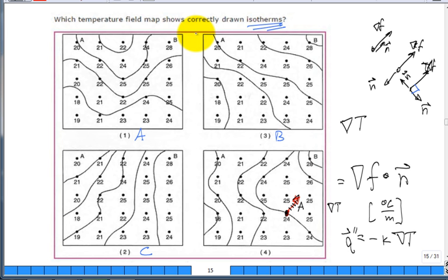True? So one goes in one direction, the other in the other. So now, I don't have time. I was going to give you a chance to catch up, those that missed it, but sorry. It's A, it's in that direction. But that's the gradient of T. And what is this direction? This is the Q vector double prime, the heat flux.